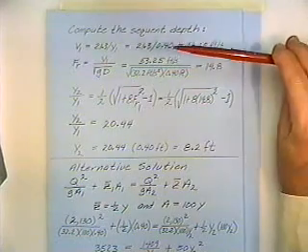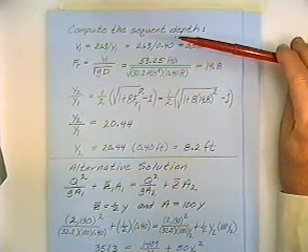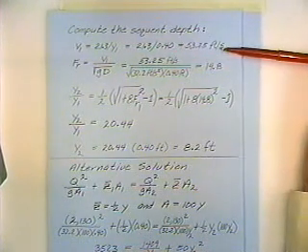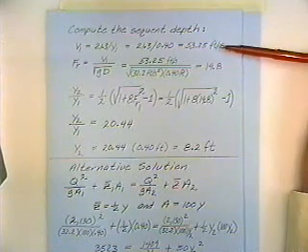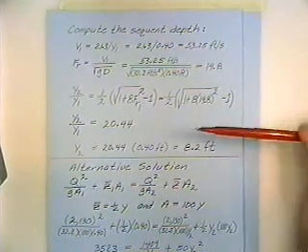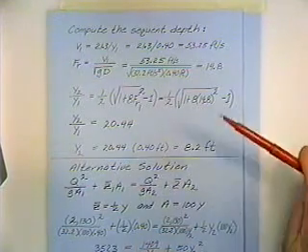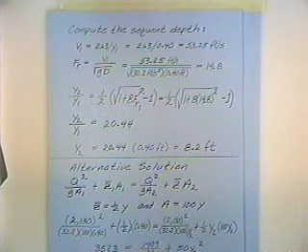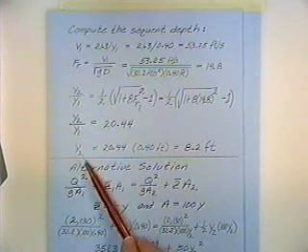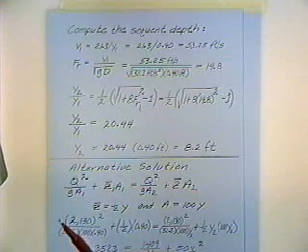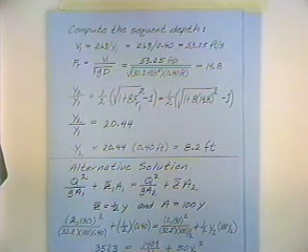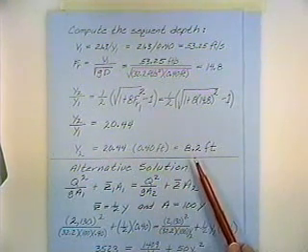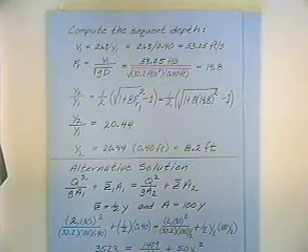And so we take our depth that we just computed, plug it into the expression from the previous page to get the velocity, use the velocity to compute the Froude number, and then plug in for the Froude number. And what this is doing for us is giving us the relationship between the depth upstream and downstream of the hydraulic jump. And so given the depth upstream of the hydraulic jump of 0.4 feet, the depth downstream of the jump is 8.2 feet.